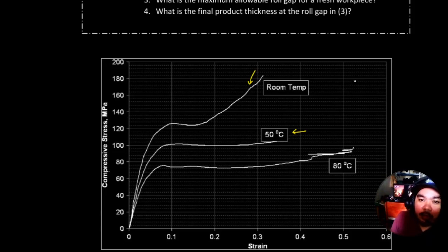So it seems like a material property, and usually ang rule of thumb natin is yung recrystallization is equal to around 0.5 ng melting, no? So if we take the melting temperature of a metal divided by 2, then we get approximately the recrystallization temperature. So if you're working at higher than recrystallization temperature, kung mas mataas yung working temperature nyo sa recrystallization temperature, then this becomes your hot working condition, no? Tapos pag lower siya than the recrystallization temperature, then it's a cold working condition. Pero ngayon, merong new term na throw around, no? It's called your warm working condition. So, warm working condition, and this is just additional information, no?